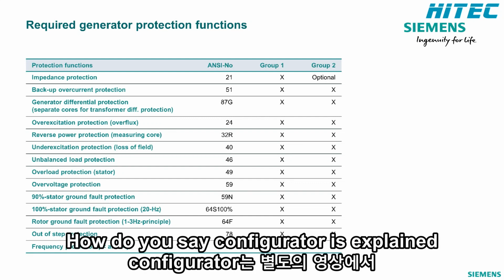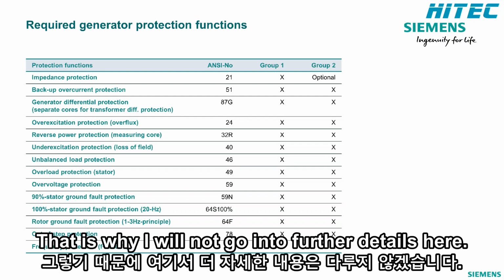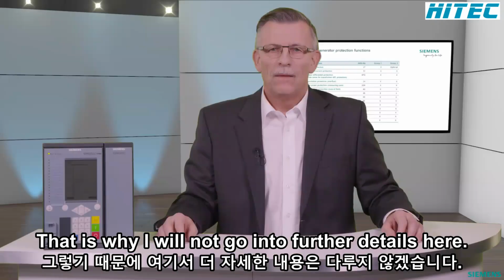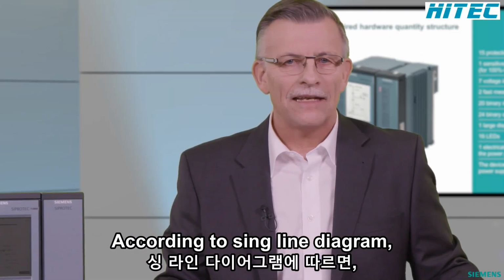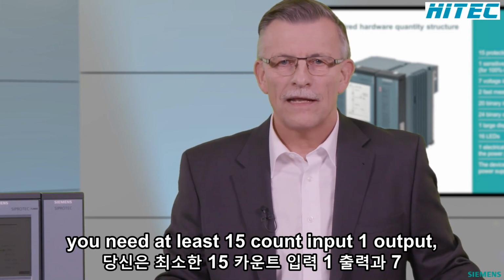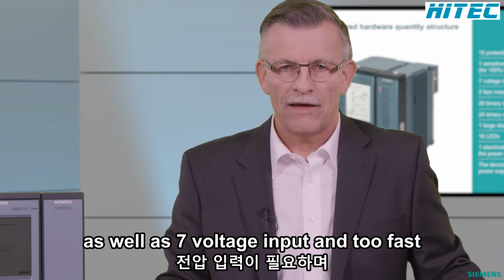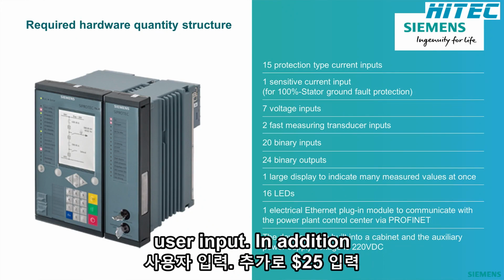How to use the configurator is explained in a separate video. That is why I will not go into further details here. Please note the following for the configuration. According to the single line diagram, you need at least 15 current inputs, 1 sensitive current input, as well as 7 voltage inputs and 2 fast measuring transducer inputs.